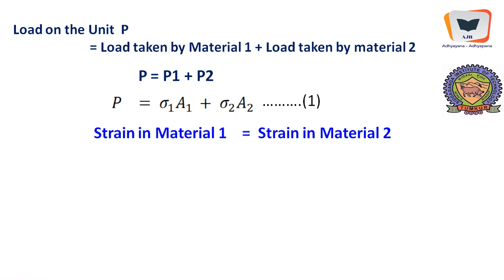For example, the reinforcement will never come out and concrete will never get compressed in the earlier instances of the load. Therefore, they will be working in tandem, receiving the load in proportion to what they are capable of. That depends upon their own capacity. However, the strain is maintained to be the same, and that is this composite action.